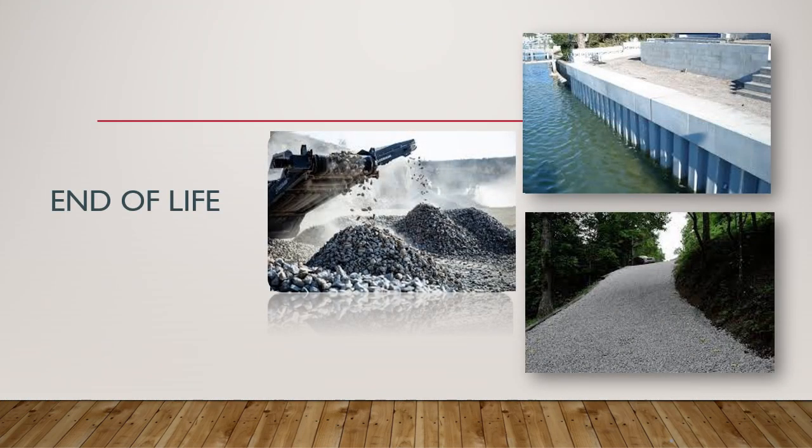At the end of life, concrete can be used in different ways. Either it can be recycled to create replacement gravel and new concrete mixes or for road base layers, or it can be reused whole, for example, in seawalls or erosion control. The demolition, however, requires energy-intensive machinery and can generate significant dust and debris.